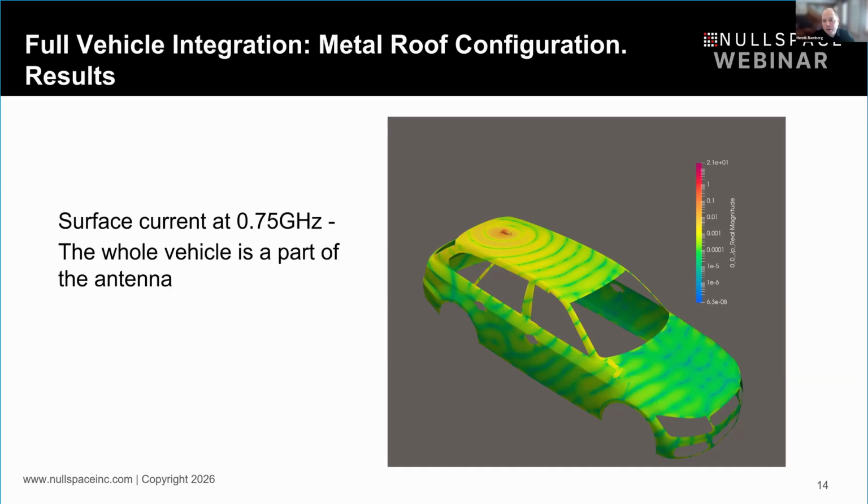We can also do near field plots and far field plots, based on more of a vehicle with a plot around it. And surface currents are sometimes really useful to look at, especially when you have local resonances. You can zoom in and see really where the problem is, what is resonating here. This is a really helpful thing to be able to do.